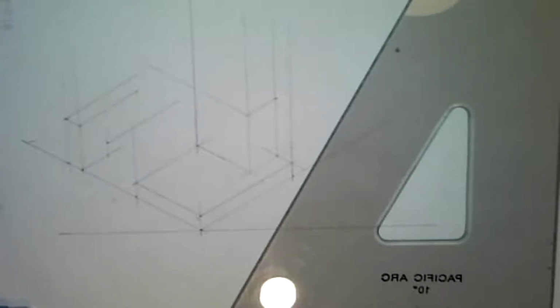So now I see that you already have the guidelines for all of your views. What I want you to do now is turn all of these construction lines into wonderful, thin, dark, consistent secondary lines. And for any of the different surfaces, make sure they have the lines in between them. Okay, let's talk about that.